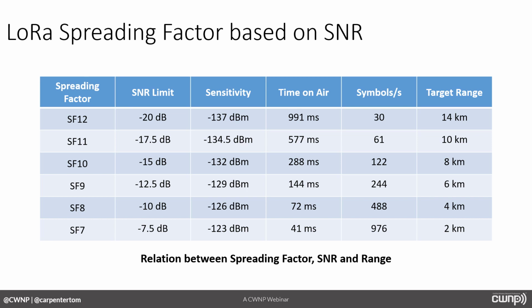Because if you study Wi-Fi, you know you're always looking for a positive SNR, aren't you? You're looking for the signal to be 3 dB greater than the noise, or 6 dB, or 12 dB greater than the noise. But the signal is always greater than the noise to some level. That's what you're looking for, right? But here, we can have the signal buried in the noise, and we can still get it out.